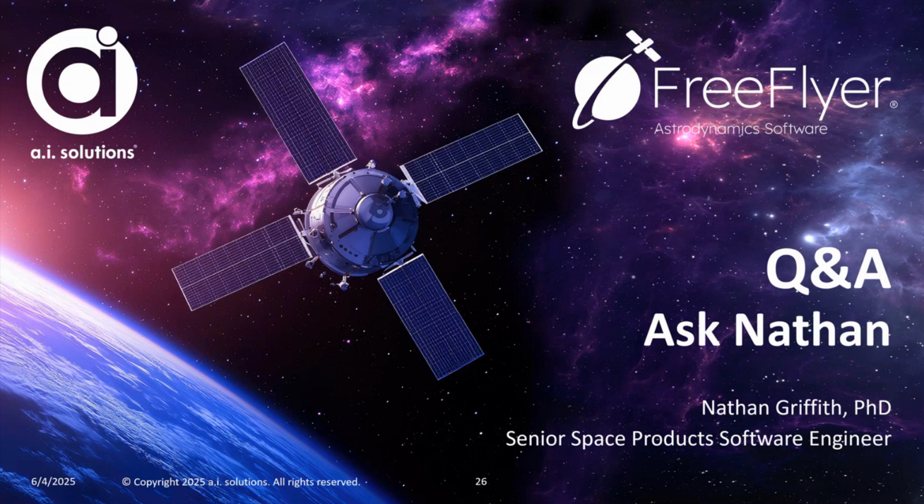It's an interesting thing because it really comes down to what kind of receiver you've chosen. So there are separate physical models for, say, APD receivers versus preamplified or heterodyne/homodyne receivers. Those react differently to the sun in the field of view, but it is something we can model. And one thing I found really surprising doing the research for this is that for certain types of receivers, preamplified and heterodyne/homodyne, it is not as big an effect as you would think to have the sun directly in the field of view. So pretty cool stuff.